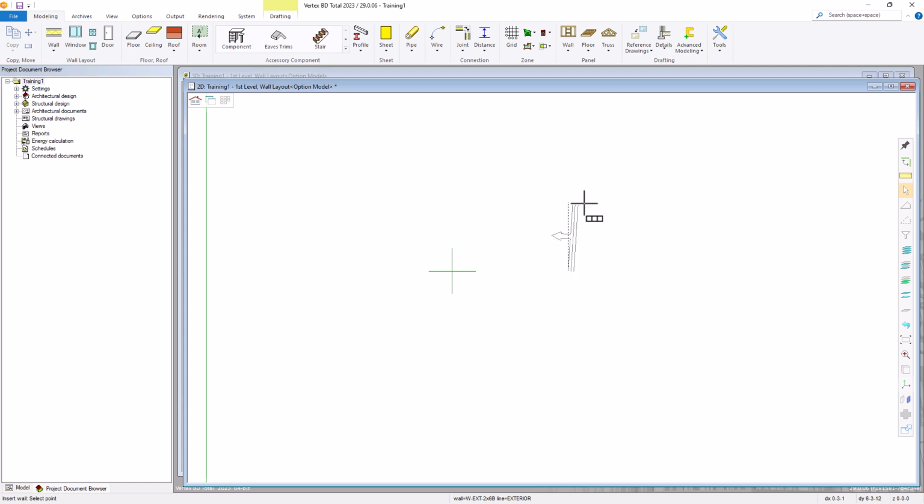Now you see that we have a wall segment linked to our cursor. Take a quick zoom in and take a look at what it looks like. If we hold it up close to vertical, you'll see we have an arrow pointing to the left. That's our exterior side, and you can tell by the amount of lines along the wall. We have a siding line and the sheathing line, and then the exterior wall. So we have more lines on the left side. Then we have a 2x6 framed wall with a center line in the middle. And then we have 2 more lines to the right, which is the drywall, the edge of the framing, and then the outside drywall line.